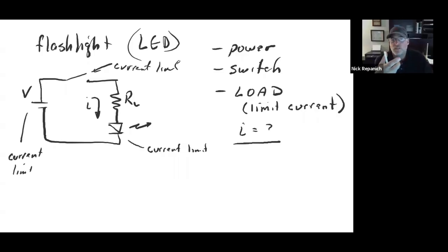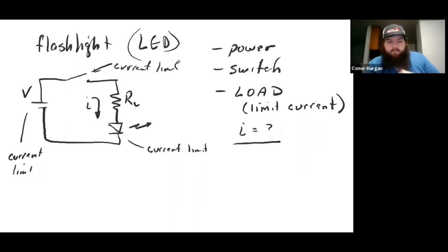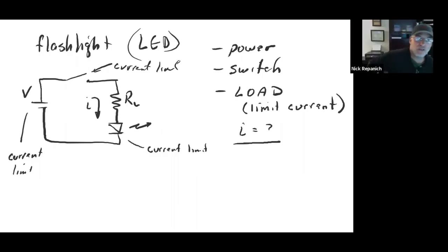Okay, and what does that mean? Current, yeah, you're looking for the current. What about the current are you looking at? It has a number, right? What's that number tell you about how much current? Does it tell you how much it will supply or how much it can supply? Can supply. Okay. How much current is going to come out of that power supply? That depends on your resistance, right? So I always want you to think about current as drawn out of it according to what the load is.